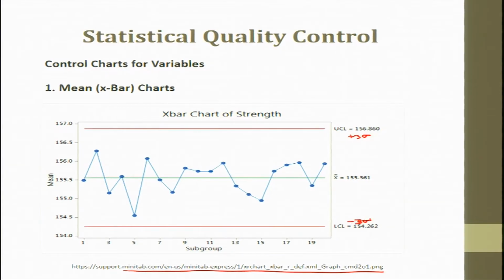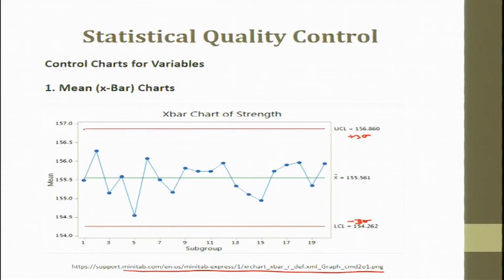But we will talk about the process capability. We can even pick some other values. In actual working, these limits are sometimes not specifically 3 sigma. This can be 3.14 sigma, minus 3.25 sigma. So, these limits are all defined. It is a kind of a normal distribution here, and I have put some skewed distribution here.